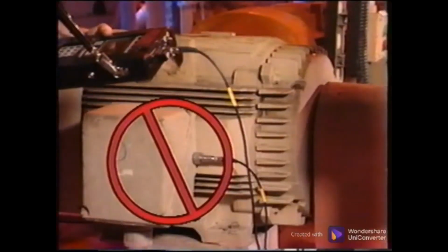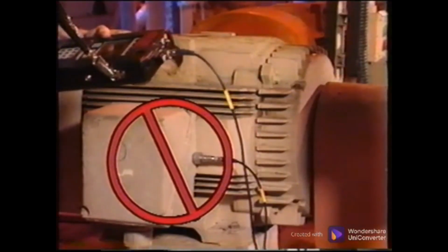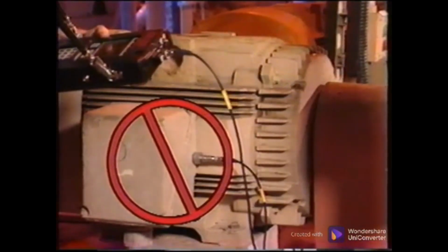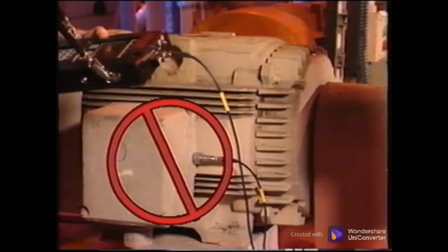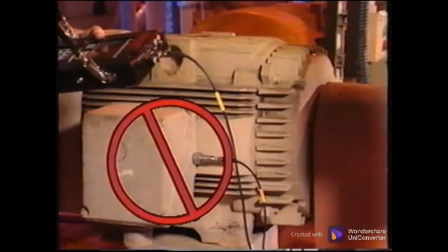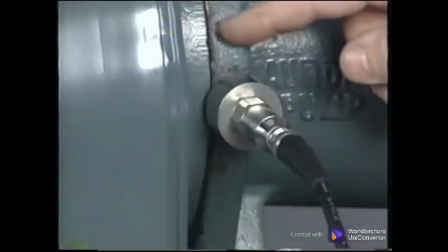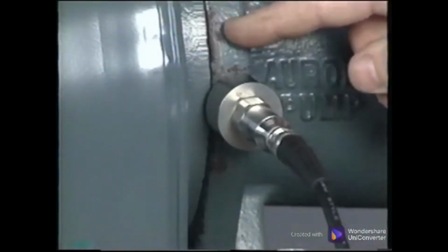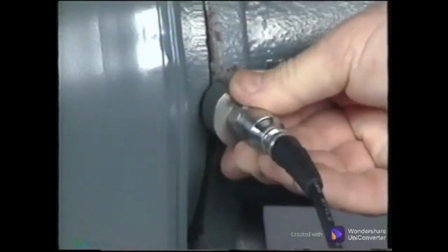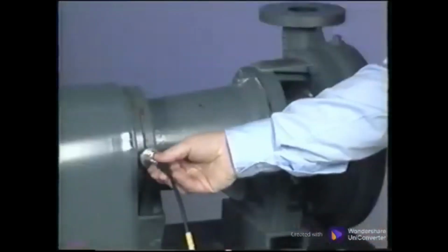Never use the electrical junction box for an axial measurement, even when it is a heavy casting of the motor housing. Data taken here will have higher levels of electrically related frequencies that may indicate motor problems that don't really exist. On the pump, the horizontal measurements should be made on this flange because the bearing is mounted directly in line here. Be sure the sensor does not cross the joint, which may cause it to rock and generate erroneous frequencies.